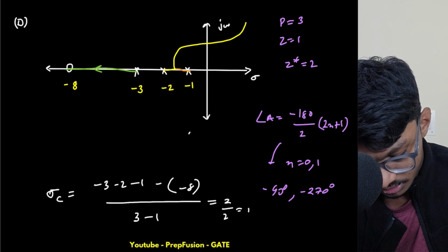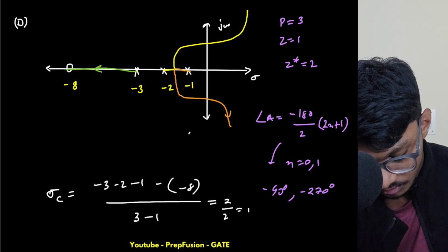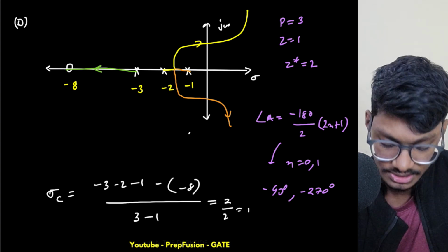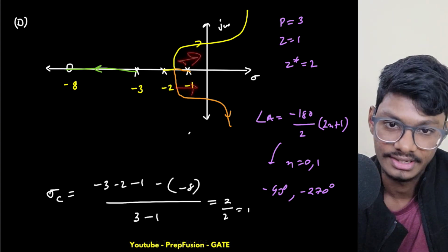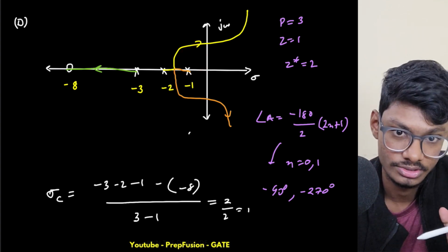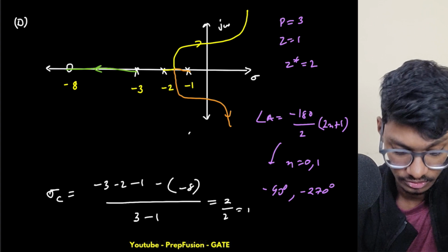So it will actually cross this axis. So anyways, it will become unstable. Okay, up until this point. So anyways, what we can see is our zeta omega n is again reducing as it is moving towards the right hand side. So zeta omega n is reducing. So settling time, 1 by zeta omega n, will increase. So settling time will also increase.